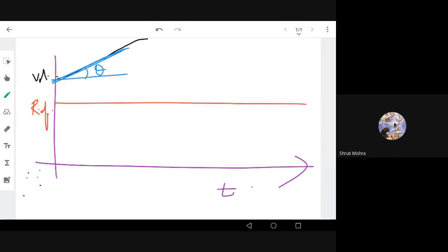So you can see that only derivative control will not help in any way. With only derivative control, if the error is zero, it will maintain the error. There's no change in the error, so the output will be zero or something. Okay, so only derivative control doesn't work. So I should always use a proportional controller with a derivative controller at least. That is called PD, proportional derivative controller.